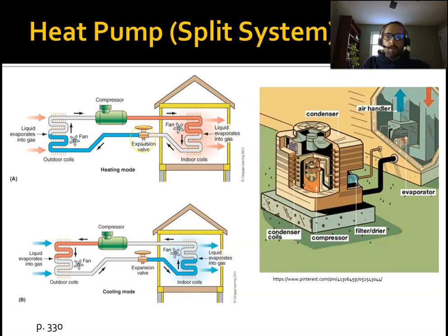And so with the heat pump, important to understand, by definition, it can heat and cool. Okay. If it's cooling only, it's called central air. And so remember, we've gone over this sort of ad nauseum, but when you evaporate, it removes heat from the building. So you may have detected a little bit of confusion in my voice there.